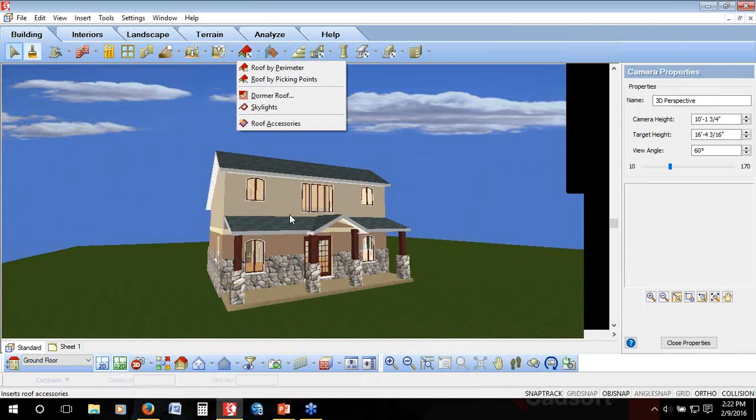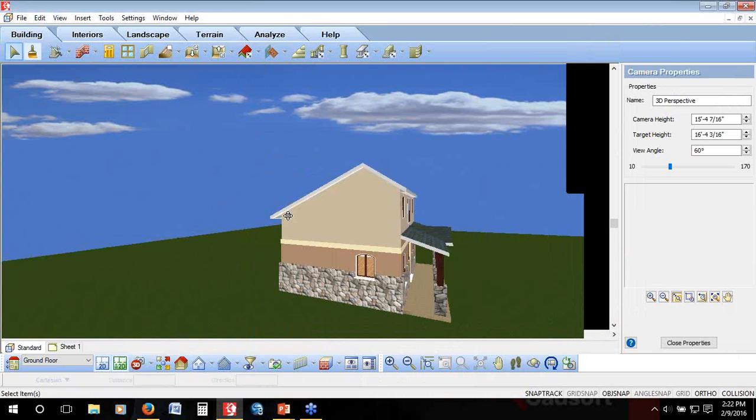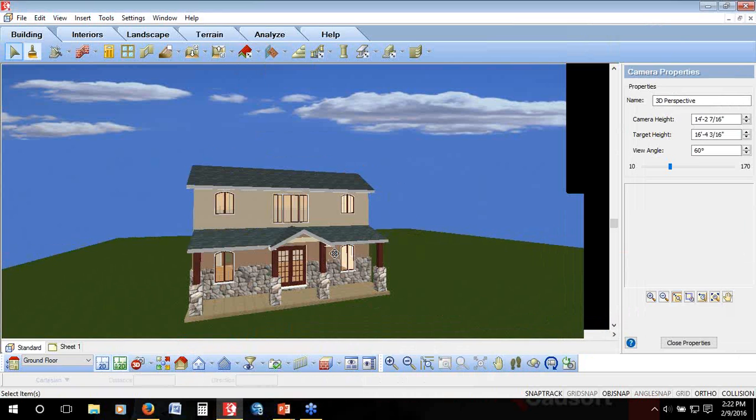Once you have all of your gables formed, then you start looking at the roof like we did on the main roof on the upper story. Is there a plate height change? Is there a pitch change? Just the same as we did at the front in this porch roof, there was a change in style at the front. So we broke the roof to accommodate our hip, gable, hip portion.